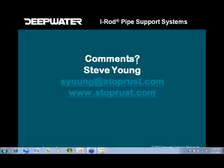Okay, let's see. Next question. Does there exist any study about the concentration of stress in the contact point with the iRod? Yes, there is, and those reports as well as the studies, again, are downloadable from our website, www.stoprust.com. And like I said, the point load for a 1-inch iRod is 8,000 pounds per rod, and the 1.5-inch rod has a 10,000 pound point load. Again, downloadable.